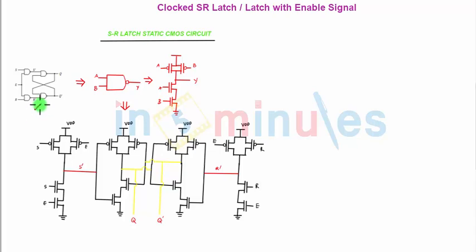We also saw the implementation of the same at the static CMOS style level, where we labeled all these 4 NANDs like NAND 1, NAND 2, NAND 3, NAND 4 respectively. We also knew how to implement a CMOS NAND, and we replaced the gate level diagrams with the transistor level diagrams and just gave the inputs, labeled the outputs and made the required connections. So this we have already seen in the previous clip.